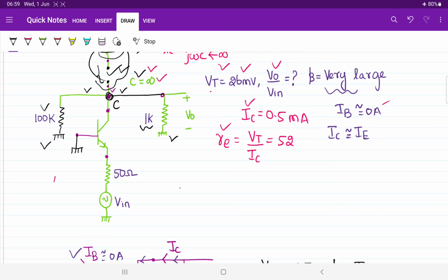Yes sir. Whenever you are having doubts, it is very important to position the resistor at the correct place. Otherwise while doing the calculations, it will automatically lead to a wrong answer. So don't forget to do that. This 100 kilo ohm and this 1 kilo ohm will be connected between the same position, collector and ground.